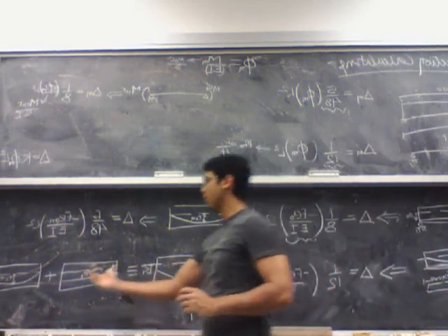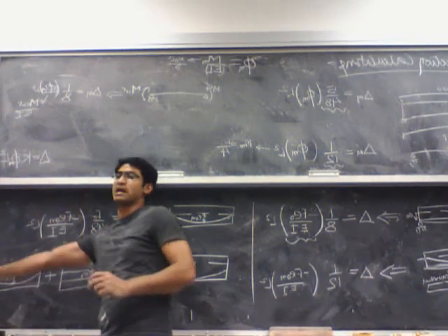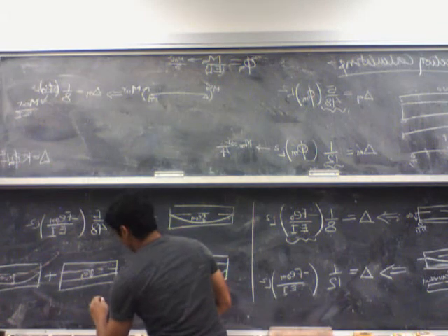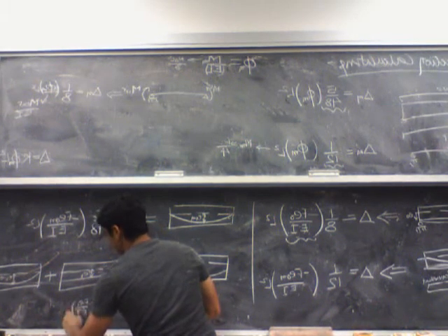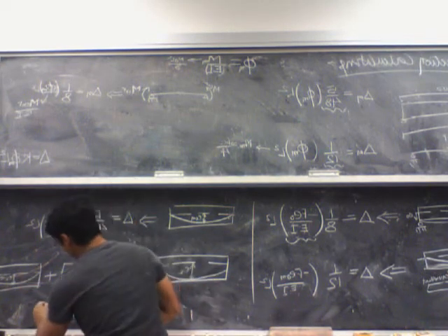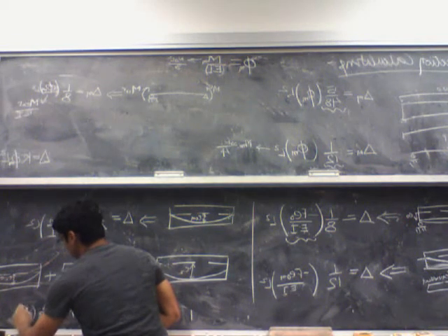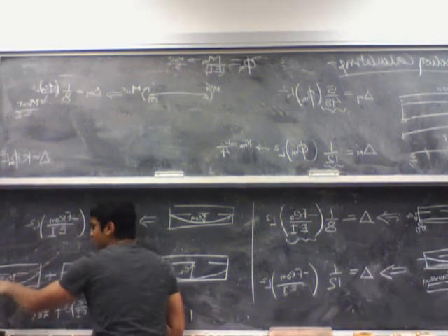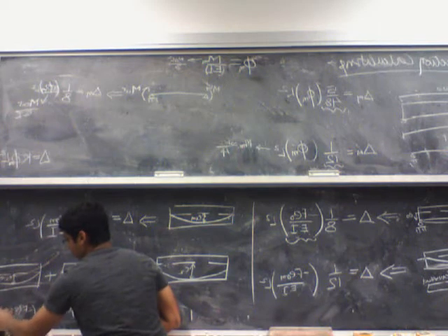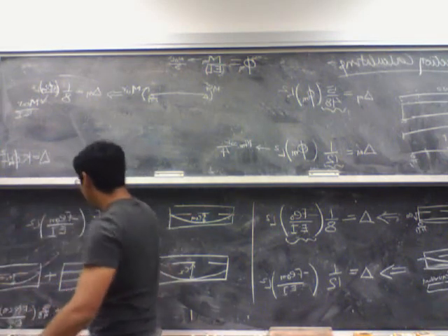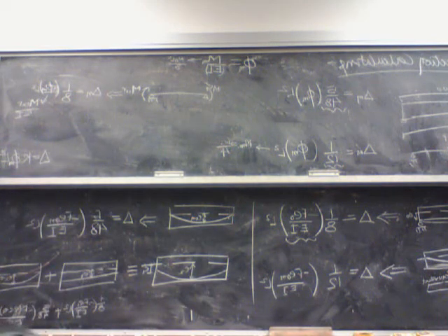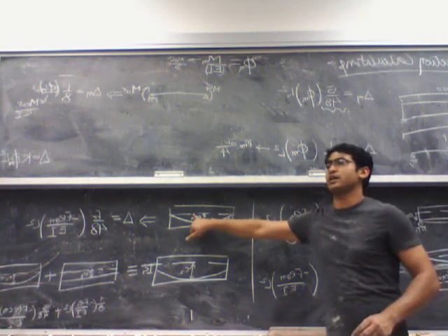Right? So this is the sum of a constant e naught and a parabolic e naught with zeros at both the ends. The deflection due to this is 1/8 minus F e1 over EI L square, plus deflection due to this, which is 5/48 minus F. What is the eccentricity at the midspan? For this case, it's e2 minus e1. So e2 minus e1 over EI L square. And the sum of these two gives me the deflection for the case where I don't have 0 eccentricity at the ends. So you can always go ahead and use the superposition principle if you have tendons which are not these three cases.